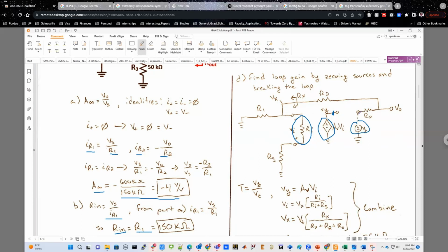The gain is a ratio of voltages at point B over point A, right? So the gain does not change depending on the value of the voltage, which can be anything. The input voltage can be anything. It could be 1 volt, it could be 1 millivolt, it could be 1000 volts, but the gain will remain the same because the gain is just a ratio of the resistances. More questions? What would you say is the best methodology?